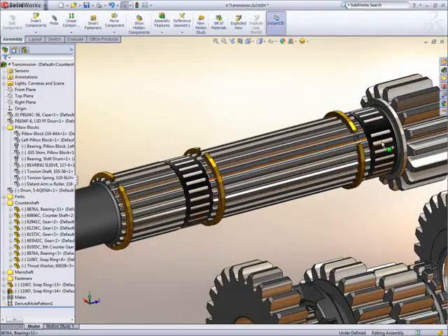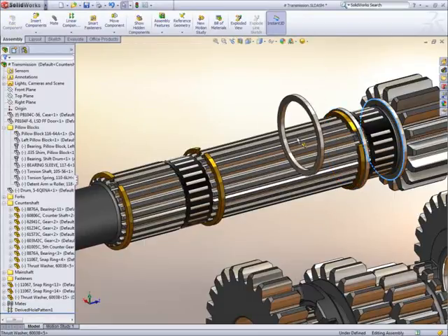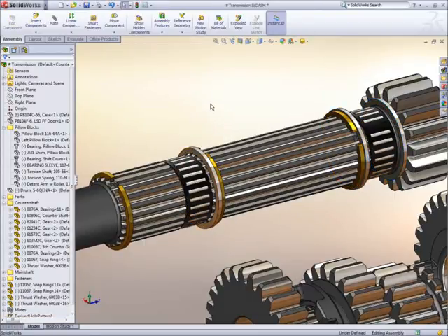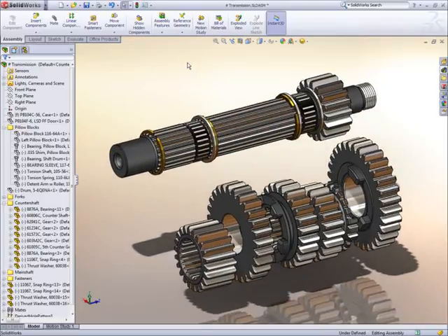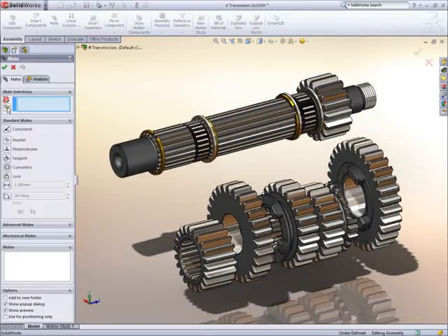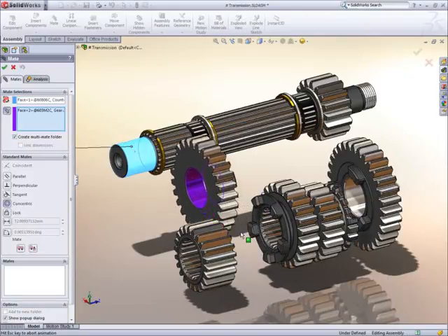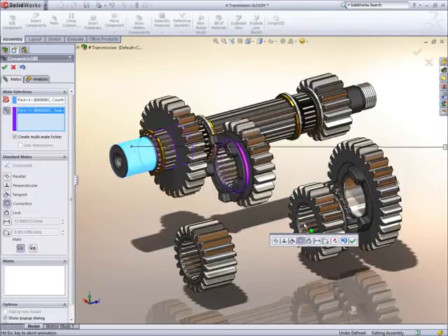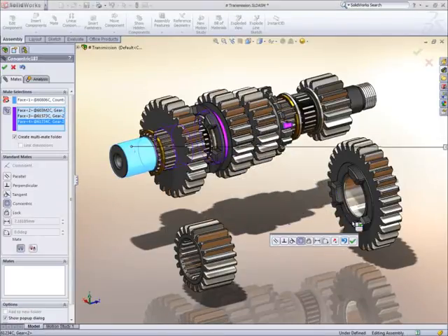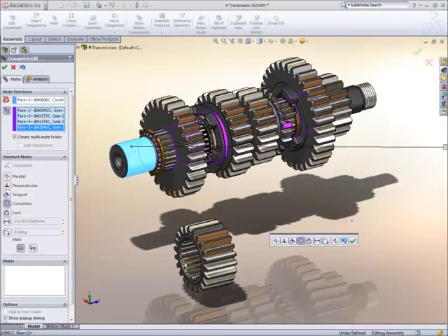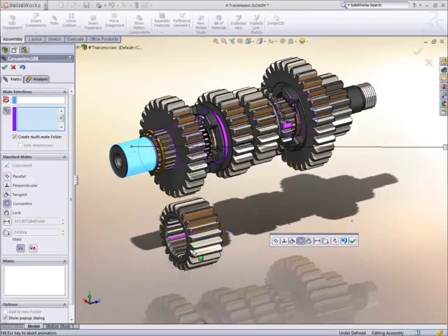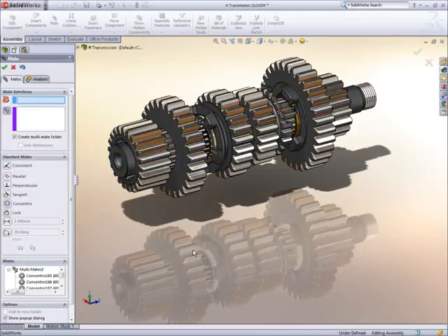This technique is perfect for when copy with mates cannot be used because there are no common component references. To add the gears onto the shaft, we need to make them all concentric. To reduce the number of mouse clicks, SOLIDWORKS has a multi-mate option where one single common reference can be reused any number of times, and the mates can also be grouped into one single feature, making them easy to edit and easy to organise, especially when building assembly configurations.